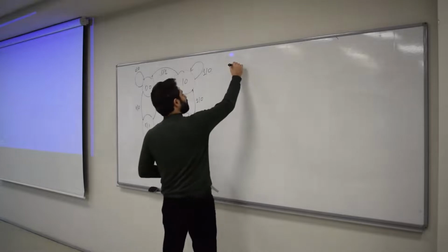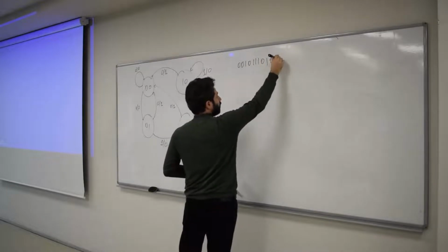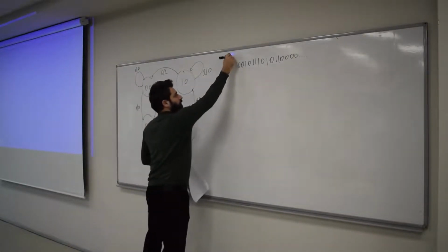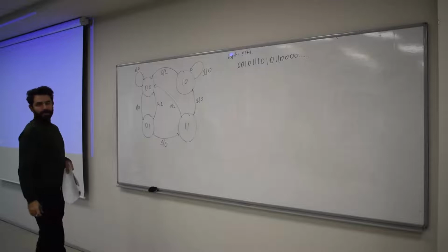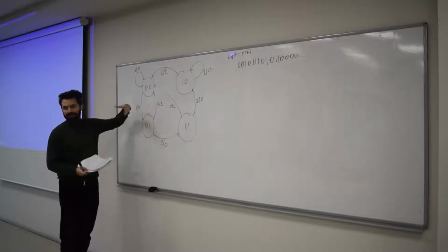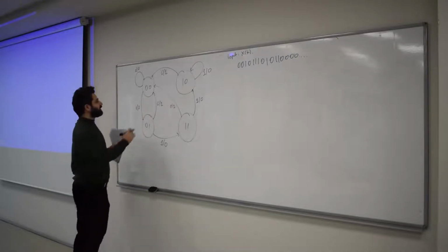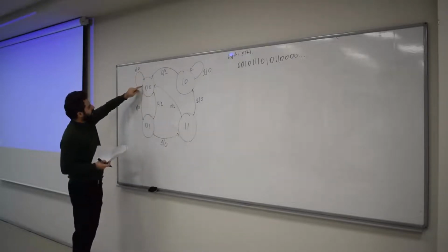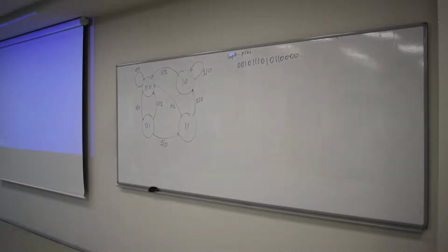Okay, but we'll see. So let's suppose that I have got the following input: 0, 0, 1, 0, 1, 1, 1, 0, 1, 0, 1, 1, 0, 0, 0, 0. Okay? Let's see. If this is your input, in other words, this is your xt. If you know the finite state machine representation, this is also called finite state machine representation, or state diagram, I mean both work, you can actually generate the outputs if you know the inputs. Because this basically says that, let us start with state 0, 0. If input is 0, that basically tells you you have to stay in that state and push out a y equals 0. So let me use another color and show you what's happening.